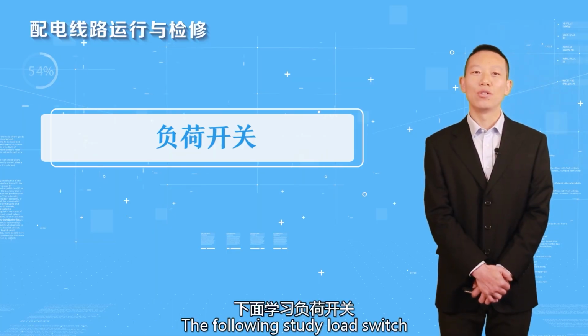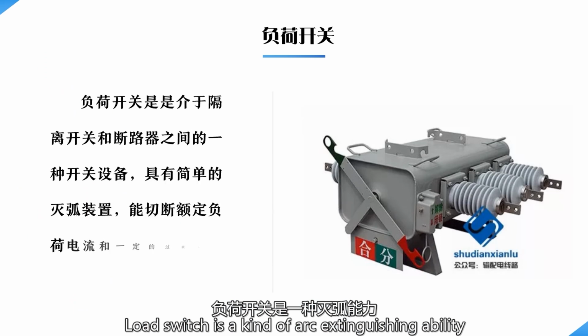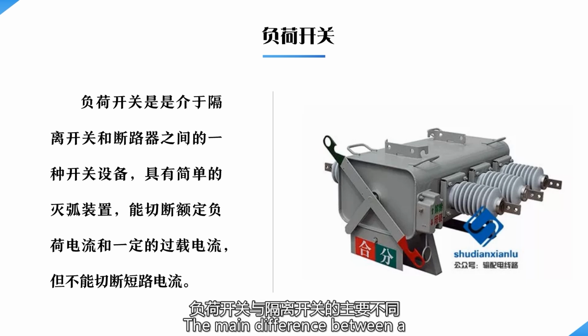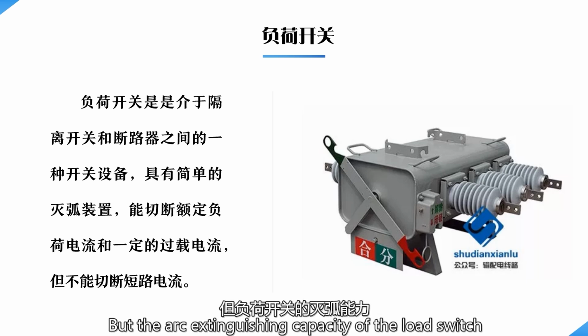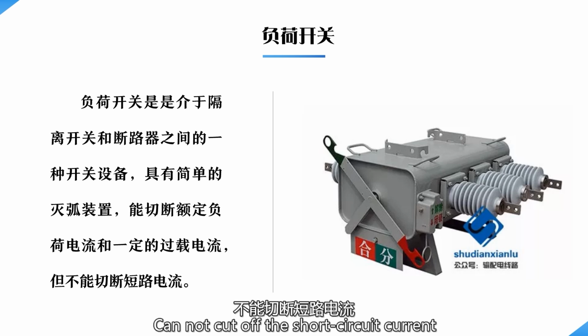The following is the load switch. A load switch is a simple switching device whose arc extinguishing ability is between the disconnecting switch and the circuit breaker. The main difference between a load switch and a disconnecting switch is that the load switch is equipped with a simple arc extinguishing device, and can connect and disconnect the load current in the circuit. But the arc extinguishing capacity of the load switch is far less than the circuit breaker, and it cannot cut off the short-circuit current.